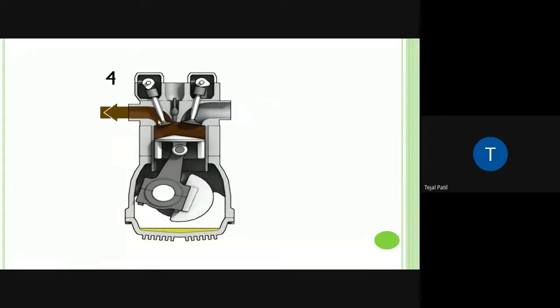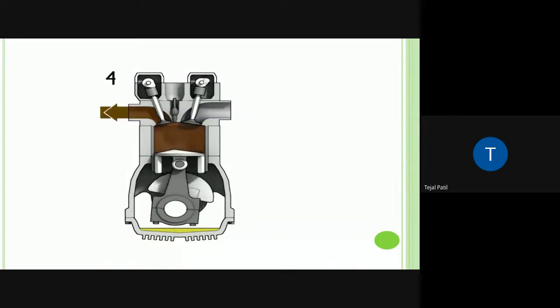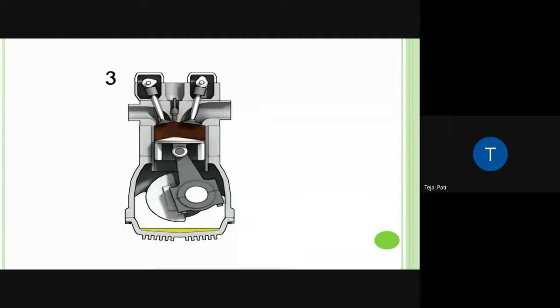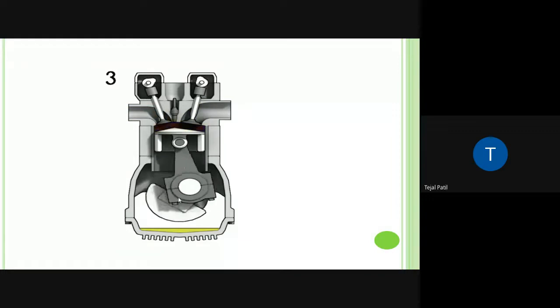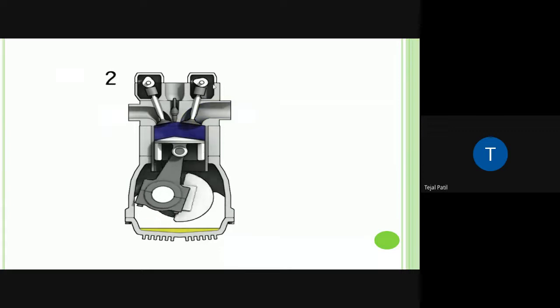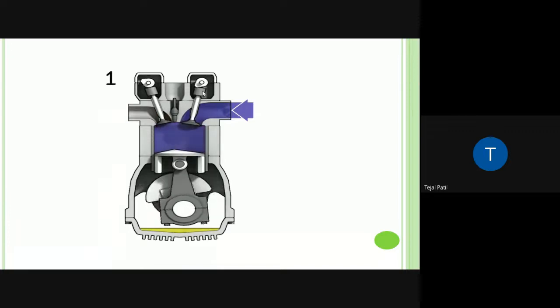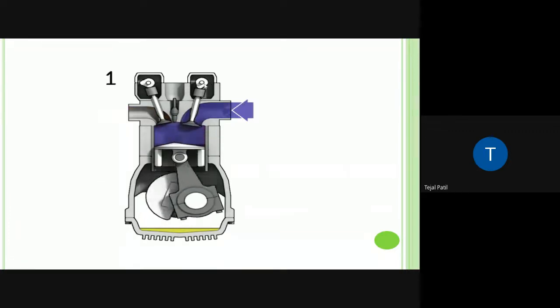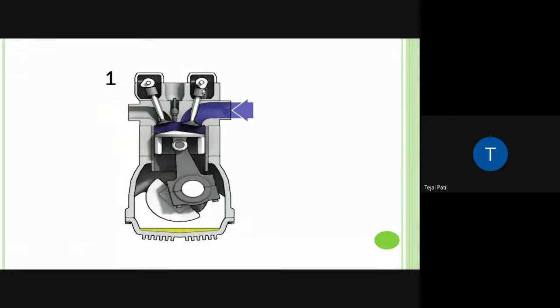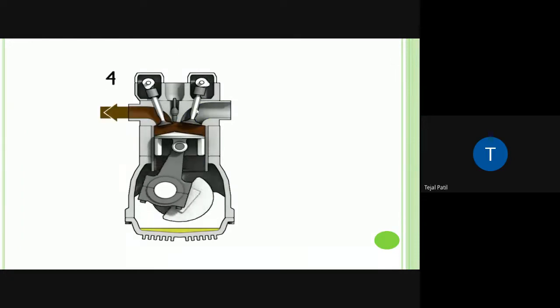Now you can see here, these are the two valves, and they are basically operated by using the cam arrangement. Okay, cam means what? This profile you can see, this is known as the cam. So this is actually operated based on the crankshaft position. Okay, so it is linked to this camshaft through different linkages, a different system is there for that. Okay, and accordingly, what will happen when this cam reaches this position? You can see when it is reaching this protruding position, the valve is opening. Okay, so this is how basically a valve can be operated.